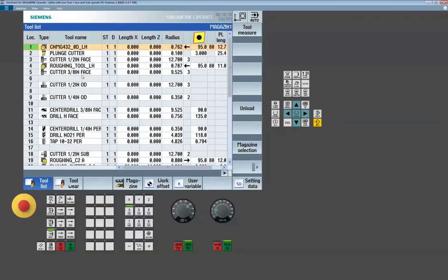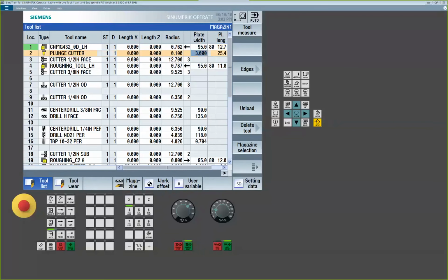In this case, I was using, I think, a plunge cutter. There you go, I have a 3 mil. So I have to know the insert width when I get to this strategy. If we're doing it in CAM, we want to make sure that whatever value I used in the CAM for my insert width is mimicked here. You can certainly give yourself a little extra stock to anticipate some slight variance, but not a lot. You have to be really close here. This pretty much has to be on.